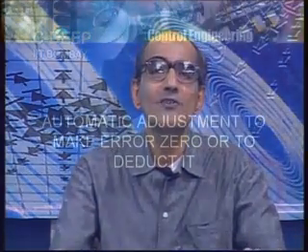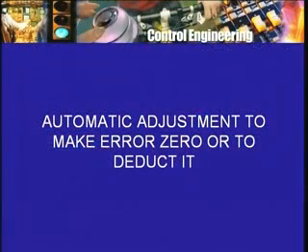And if you want to make it automatic, you have to see what's actually going on. That seeing what is actually going on is feedback, and then you have to make an adjustment which is based on that feedback. The speed is not correct, it is less, I have to increase it, or it is more, I have to decrease it, so I have to make some adjustment somewhere. This adjustment we want to be done automatically, and that's the whole purpose of the feedback idea.